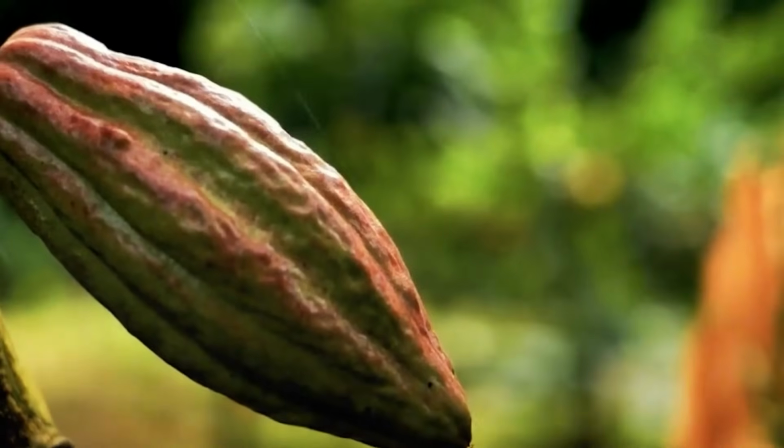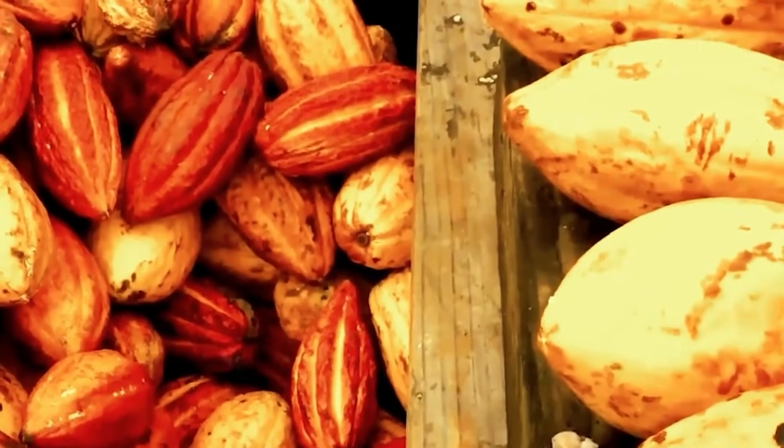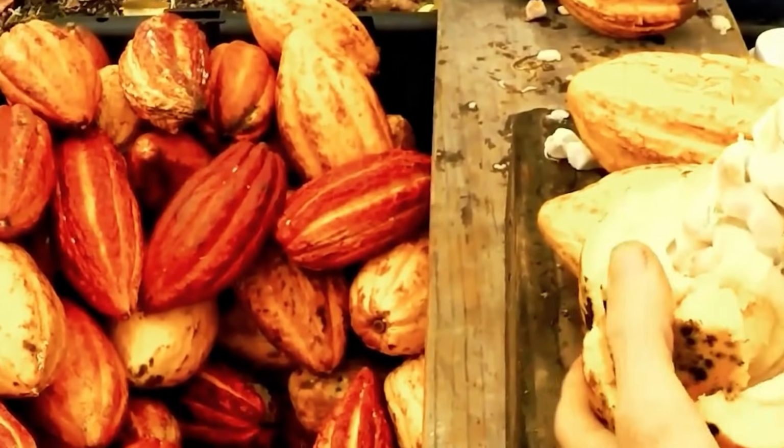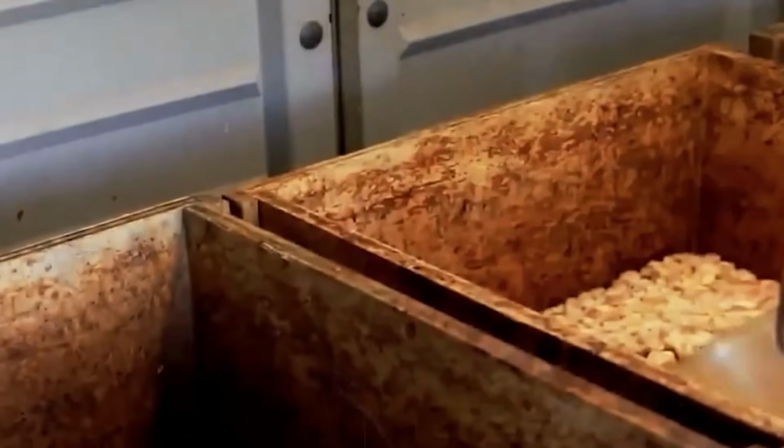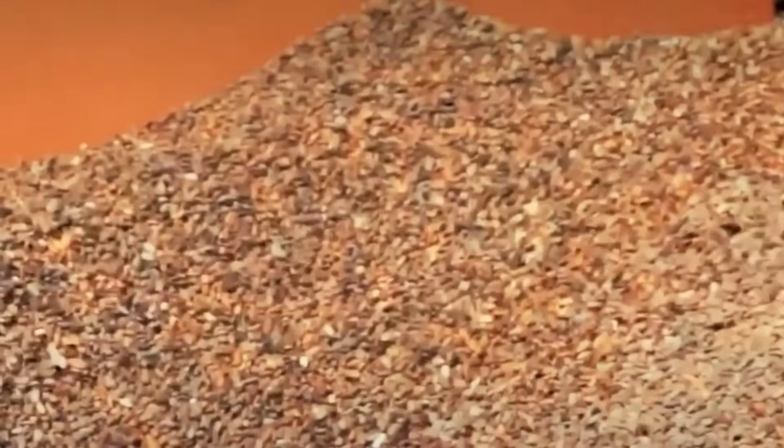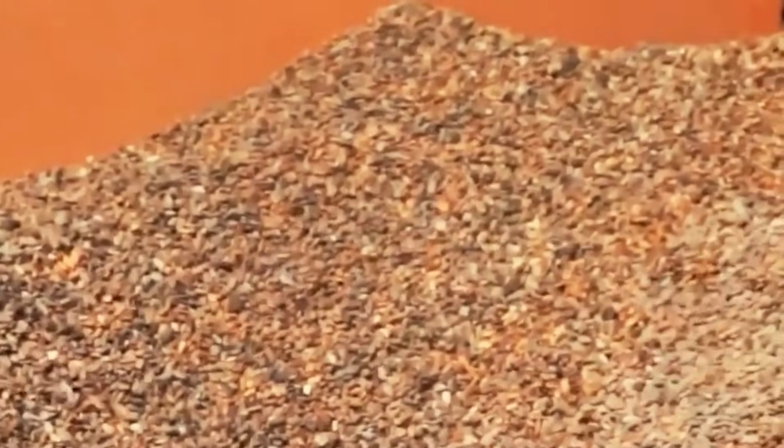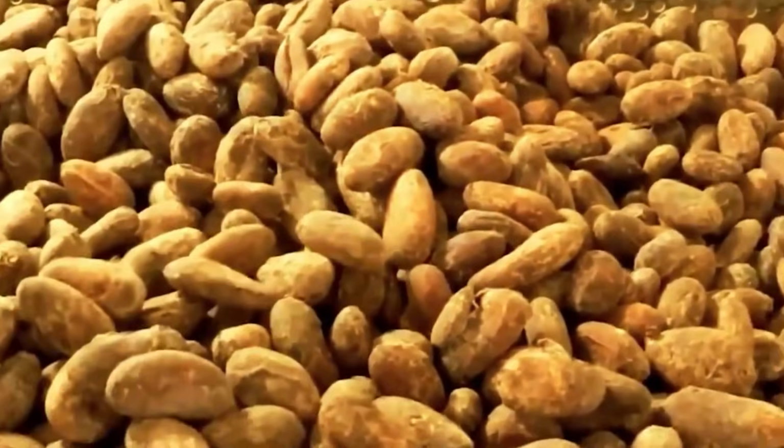Parallel to biscuit preparation, caramel is cooked in a steam-jacketed stainless steel cooker equipped with a vacuum system. The caramel mixture consists of glucose syrup, refined sugar, sweetened condensed milk, vegetable fat, and emulsifiers. The blend is heated to between 115 degrees Celsius and 120 degrees Celsius under continuous agitation to achieve a homogeneous, smooth consistency. A vacuum stage follows to reduce moisture content and prevent Maillard browning beyond the desired level.